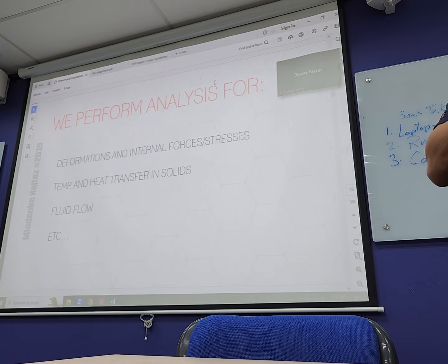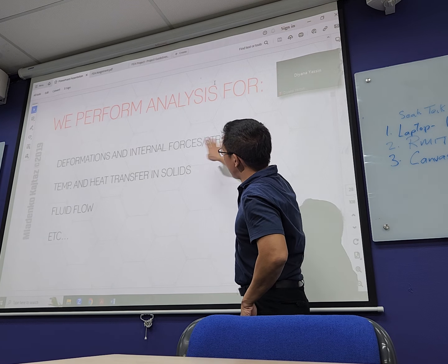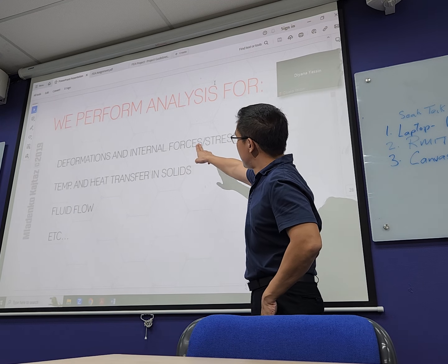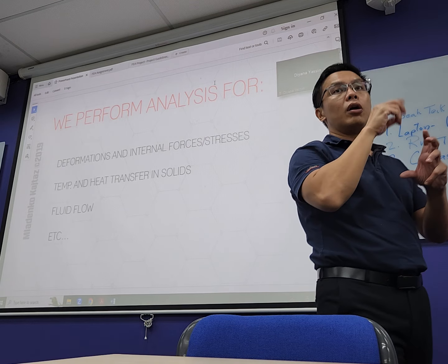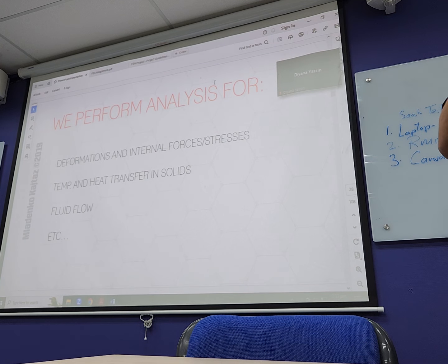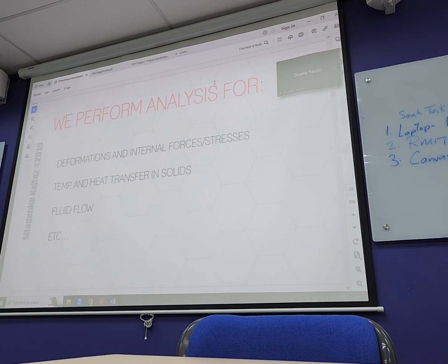What we are doing in this course is a very introductory course. So all the problems that we are solving are your stiffness in terms of your force and your displacement. But really the finite element engine works for a lot of things, like temperature, not just force and displacement. You can solve for other things, for example thermodynamics, your heat flux and your temperature gradient. The same model could be used for different types of analysis.